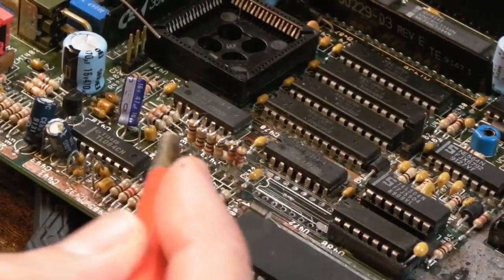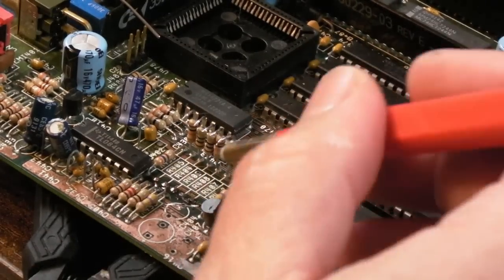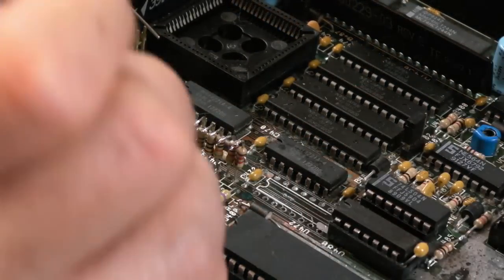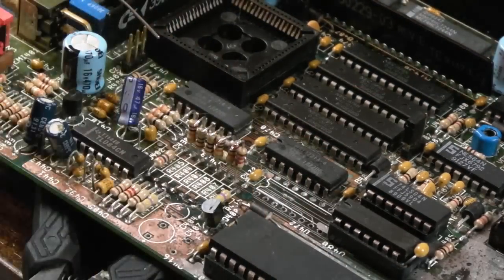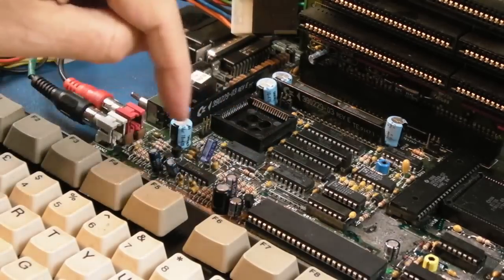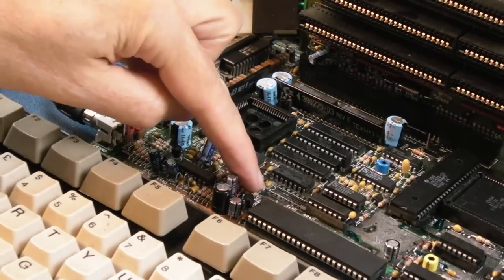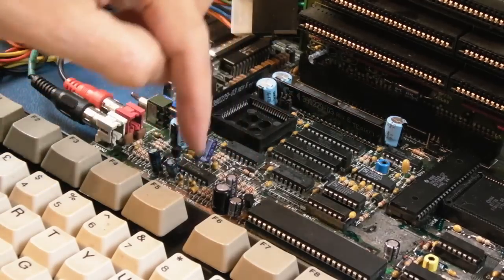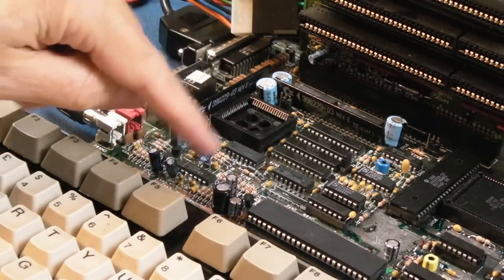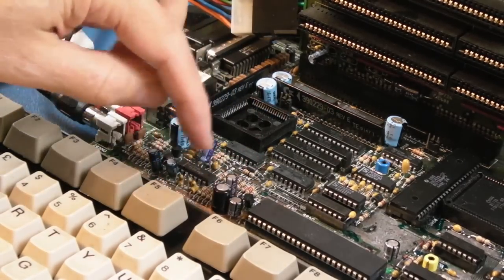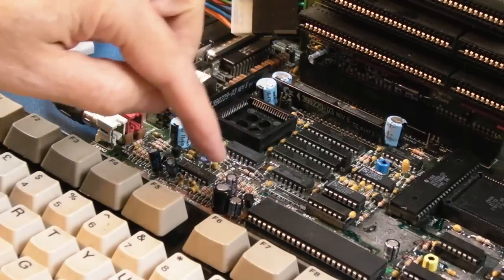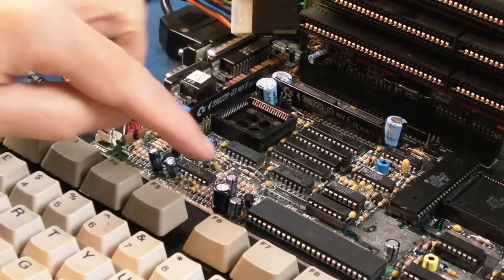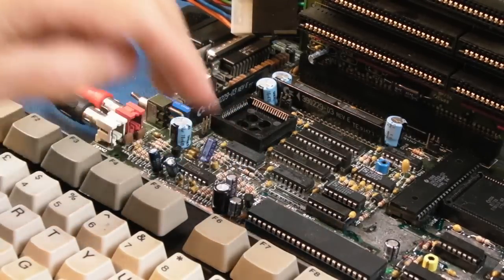You can then inspect on the underside, clean them all up, but most importantly I can now get access to the 2 vias that are under here. So all back together here, I'll give you a close look at this area in a minute. So yeah, plugged 3 vias under there, another via, 4 vias in total I think. Cleaned all around that area, got rid of all of the corrosion off the surface. We're just back to copper, but I'll probably put some clear nail polish around that area and then replace these 3 caps. I've got Nichicon and 2 Panasonics there.